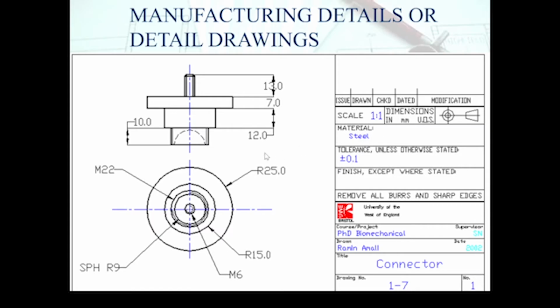What material would you like that to be manufactured from? So that's steel of some grade, not specified here. What kind of tolerances we're looking for. Tolerances generally means whenever we have a number like this here, what that really means is we are okay with 11.9 or 12.1. So if the manufactured piece doesn't really have that as a 12 millimeter dimension, it will still work as long as that's within the tolerance. So that's basically the forgiveness limit. As long as that's within the tolerance of plus minus 0.1 of a mil, that will still work.